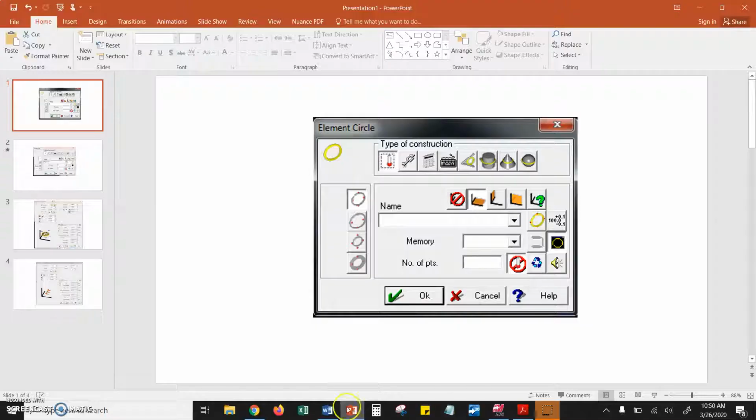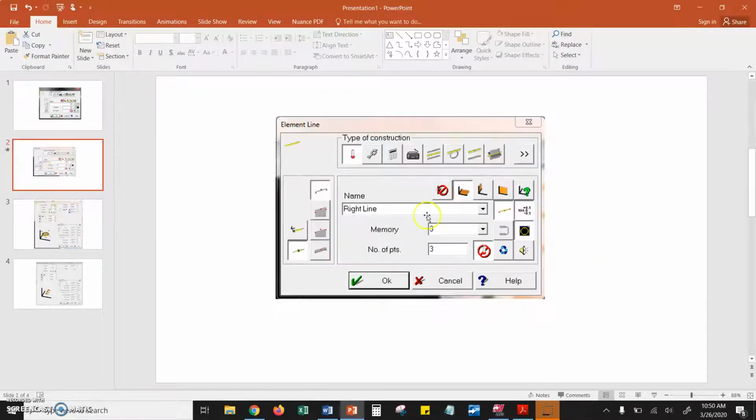So how does this translate into the CMM software? Well, here I've pulled up a dialog for element line. We can see that up here in the upper left of the dialog, and notice that we have these three different projection planes. The CMM software does it a little bit backwards, in my opinion. We have the top plane, which would be called the XY plane. I think this should be the front plane next, but the CMM software calls that the right plane.